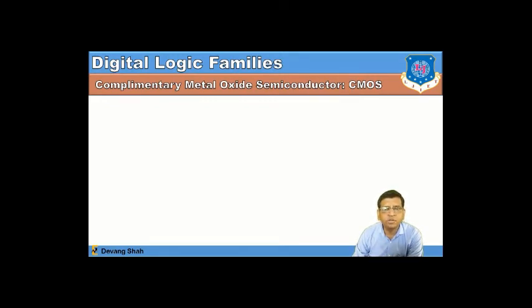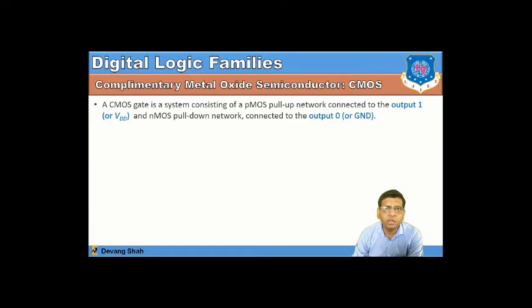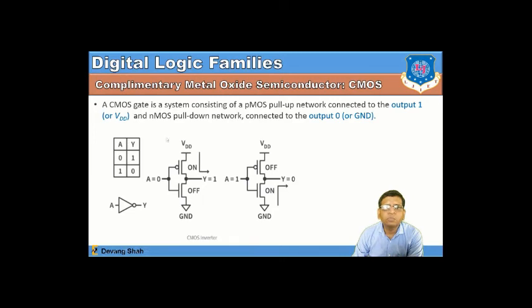complementary metal oxide semiconductor family, where all this logic is shifted to only transistors, and those transistors are now called NMOS or PMOS, right? So ultimately it's metal oxide semiconductor transistors where diodes were gone, the BJT based transistors were gone, resistors were gone, only the CMOS logic exclusively comes into the picture, where CMOS contains the P channel metal oxide semiconductor and N channel metal oxide semiconductor, and we are taking both as complementary